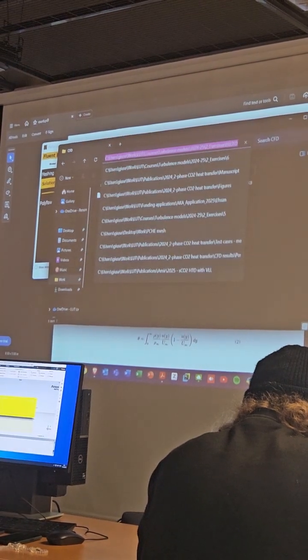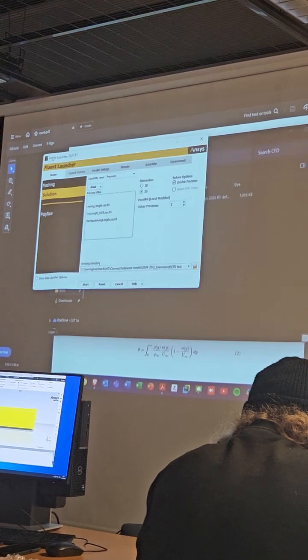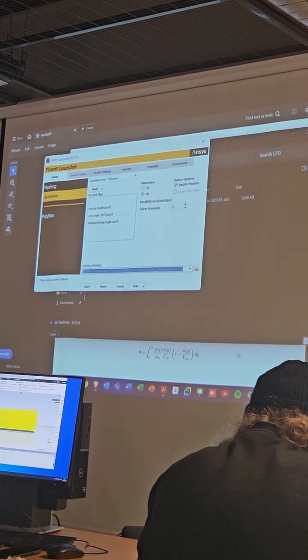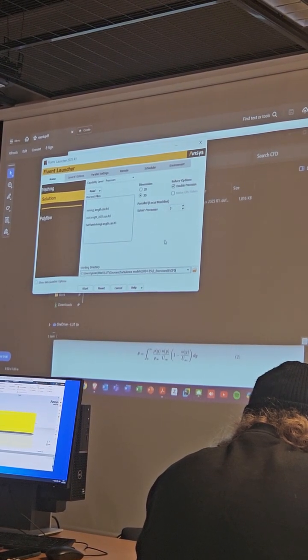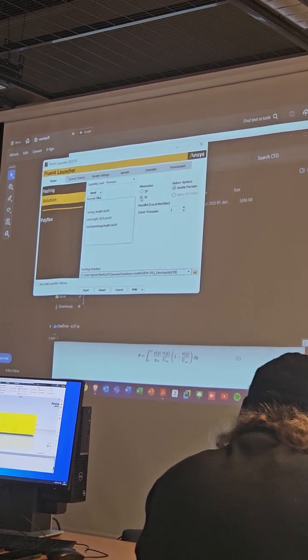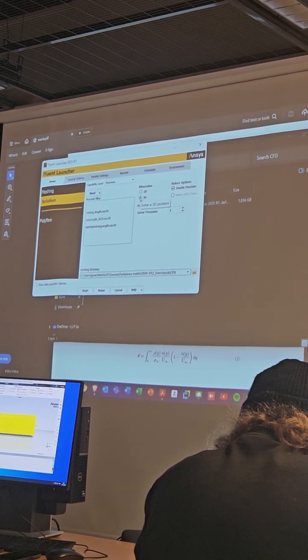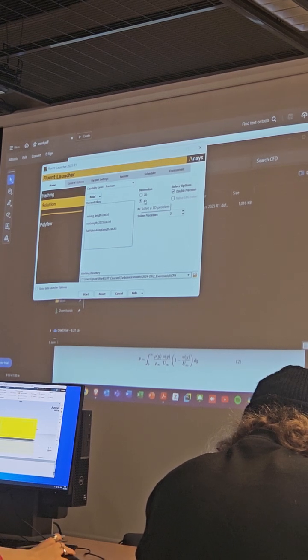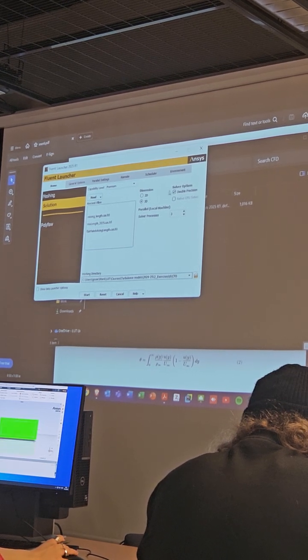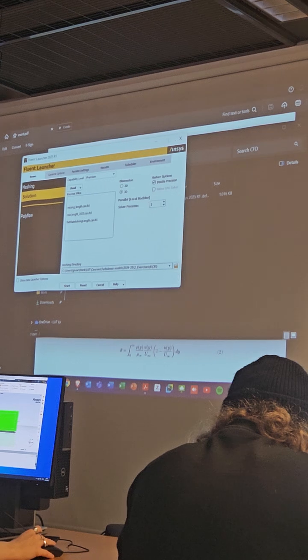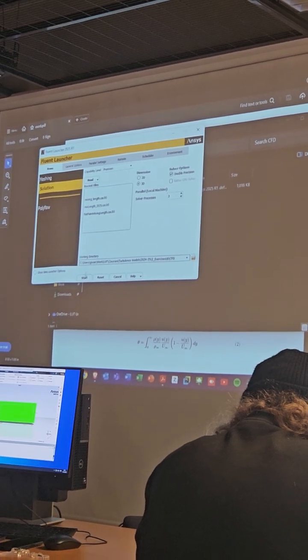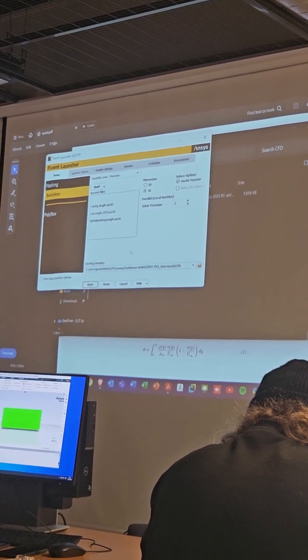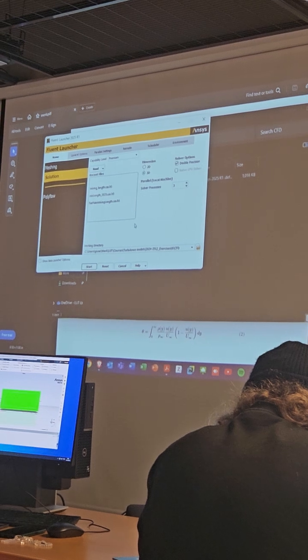So I'll just copy this path in the working directory. These are always 3D cases, even though they are quasi 2D, but these are still solved like 3D cases in Fluent. Double precision, and then for solver processes I use 3. So I can start the software.